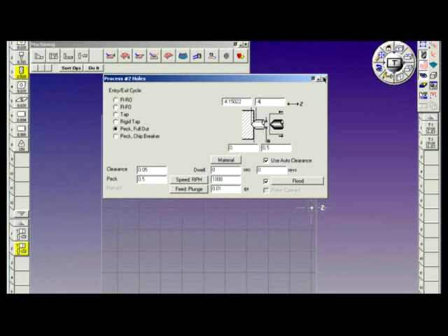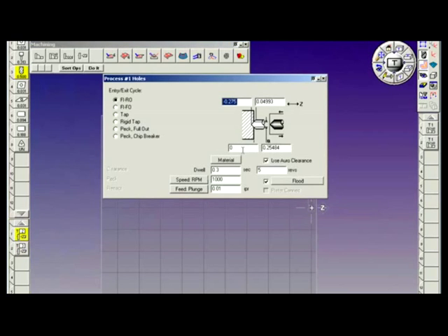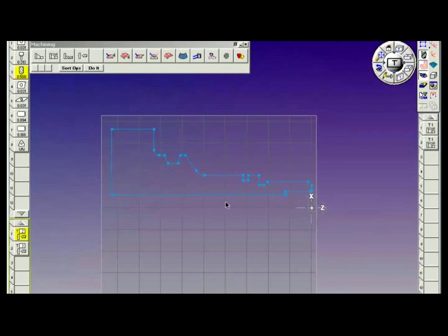We'll close the dialog. Now you notice that the Do It button is already lit up. I don't have to select anything because I have already specified where the start of the cut is at Z0. And the fact that we're in lathe ensures that we're only cutting on center line. So the Do It button is highlighted.